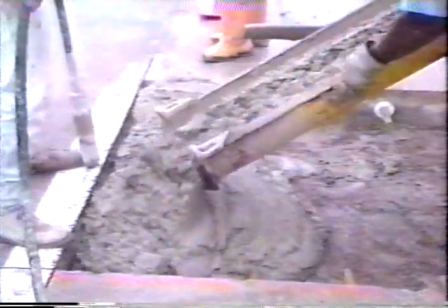Because fresh concrete contains entrapped air when it's initially placed, consolidation by mechanical internal vibration is needed to eliminate the voids. For concrete pavements to perform well, the plastic concrete must be thoroughly consolidated. Inadequate consolidation, on the other hand, leaves the concrete weak, porous, and non-durable.